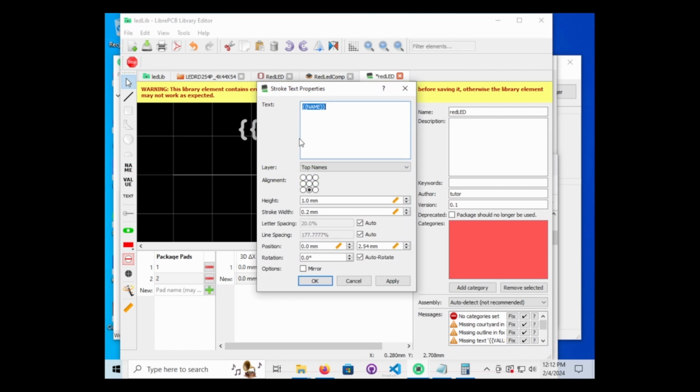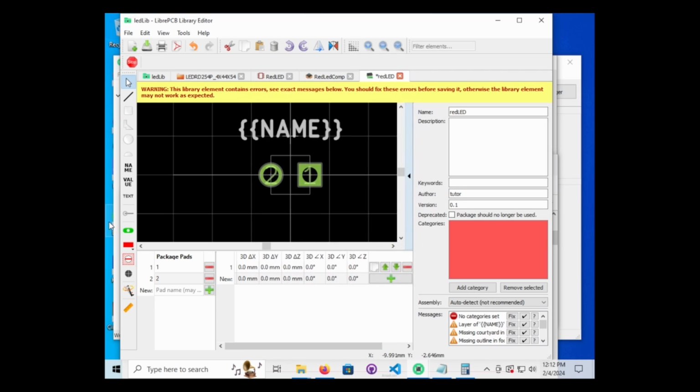And we're gonna check. The name is on the top layer. We actually want it on the top. Ooh, there's top copper, solder paste, bottom, values. They call it values. So it should be on the top values. So usually that's a silk screen layer. I don't know why they call it values, but you can do it on the silk screen layer.